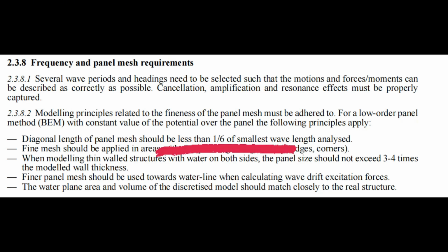For example, we can refer to DNV's RP-H103 standard, which clearly specifies the requirements for frequency analysis. It specifies the length of the mesh diagonal. It should be less than 1/6 of the minimum wavelength.